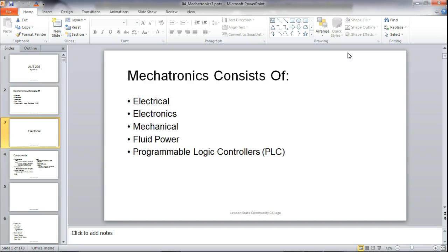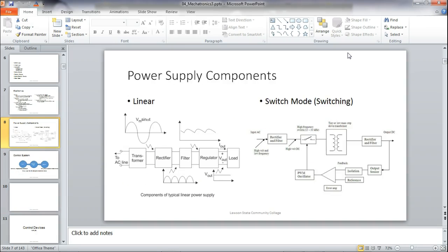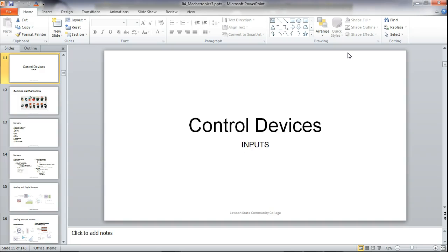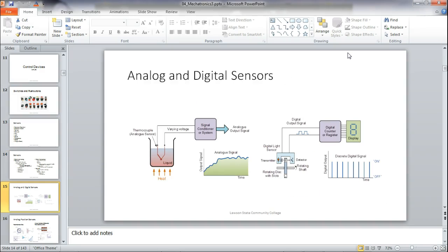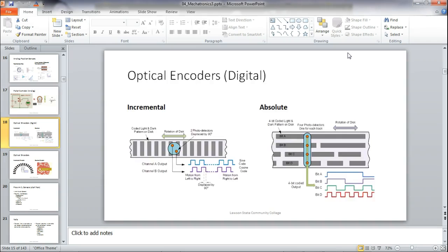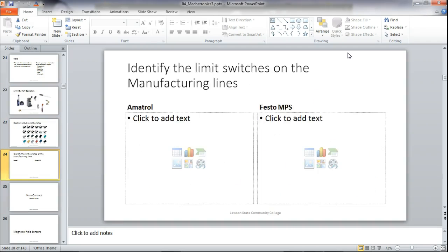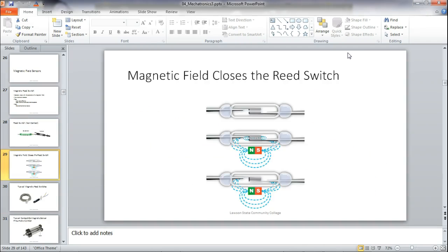Okay, y'all understand? Why? Because of the mechanics of the thing. So your steering wheel's got a limited stroke, right? Why? The wheels are only going to turn so far. So if I had something turning my steering wheel for me, it would probably be some type of actuator that had a limited stroke, right? You understand that? So it's limited by the mechanics of the thing.